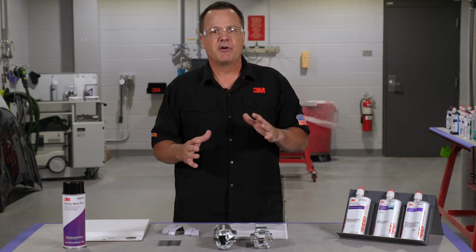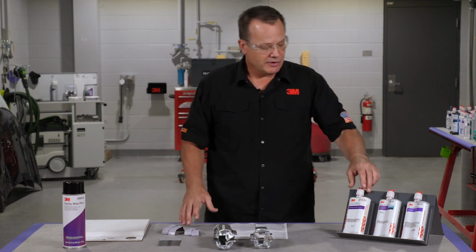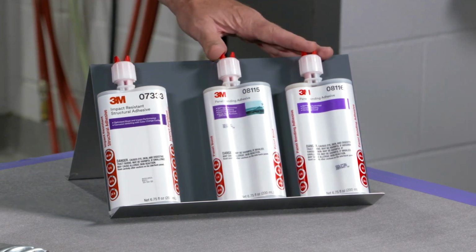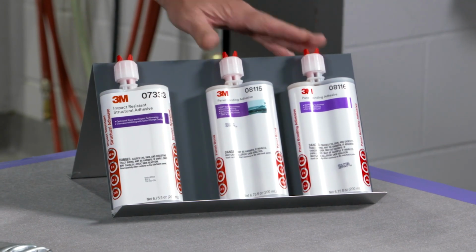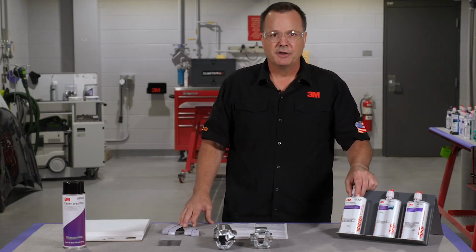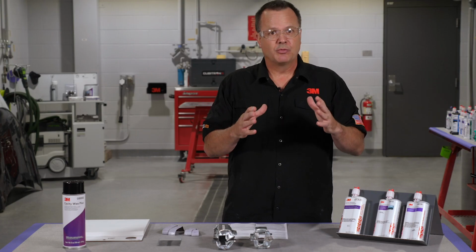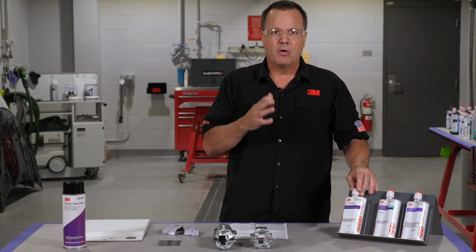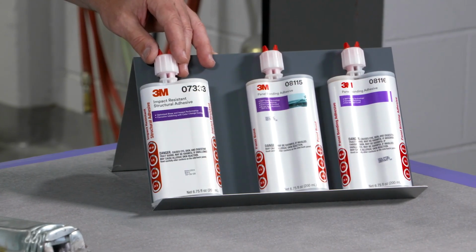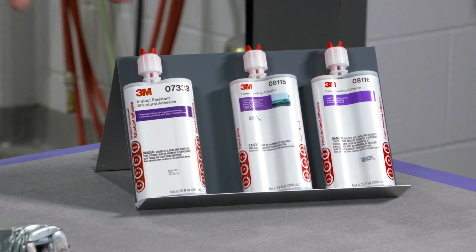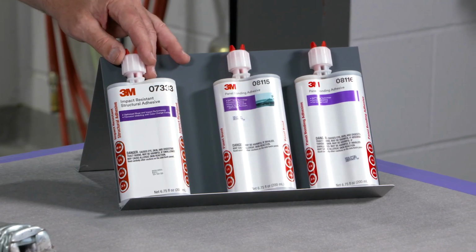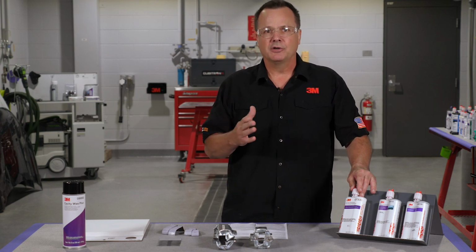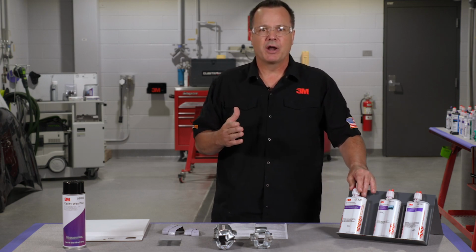Now let's talk about some very important differences. As I mentioned, we have one structural adhesive and two panel bonding adhesives, and there's a large difference between those two. So a structural adhesive is designed only to be used where the manufacturers tell us to use it. So you're going to need to specifically go to each procedure for each vehicle and specific year and find out where they recommend a structural adhesive. We don't want to use that just anywhere we feel is suitable. We have to follow the OEM recommendations.